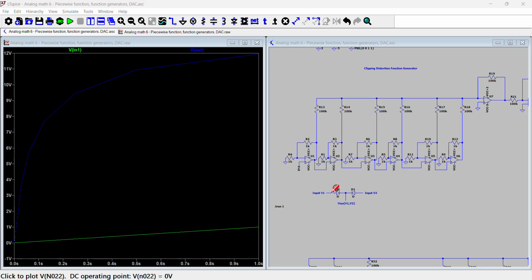So here I have an example of this. This is basically two diodes facing each other, and you have the two inputs on either side of the diode. Because diodes reverse bias in one direction and only forward bias in another direction, in the middle will only be the larger of the two voltages. So this is basically a max function.